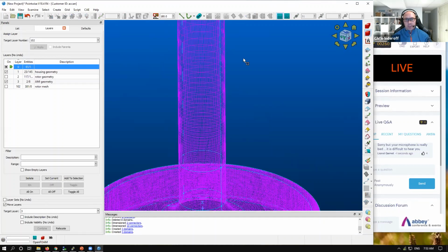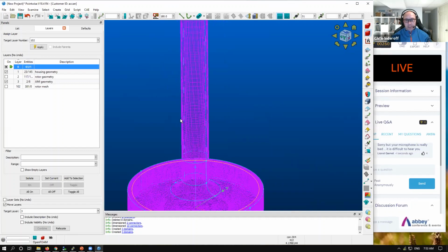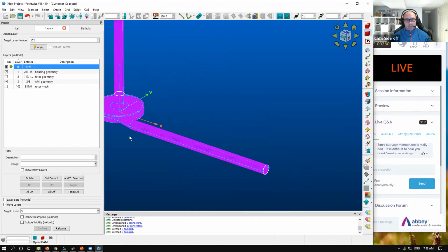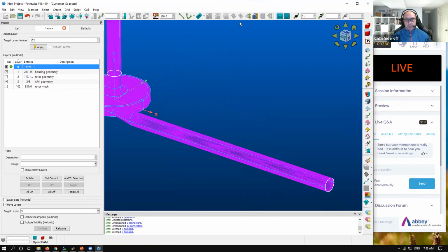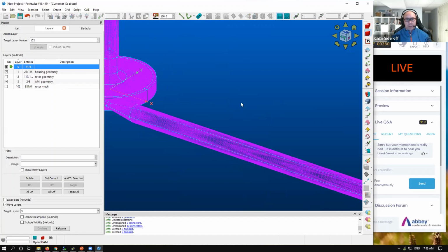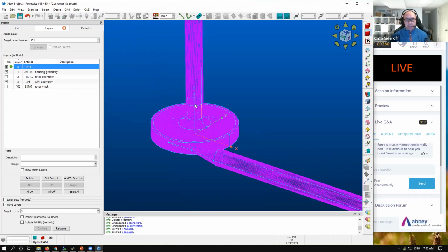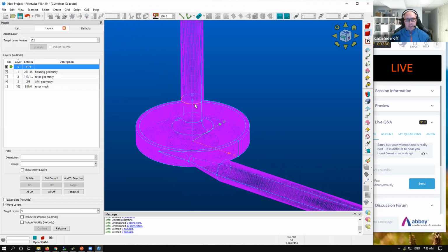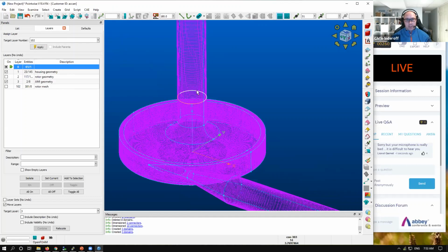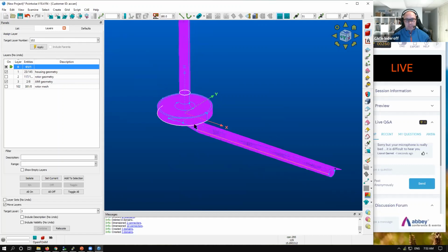The other thing I need to do is cap off these ends with a structured domain. Actually, I can't do that yet. The reason is that to make a structured domain, I need to have 4 edges, and right now at the circular regions I only have 2 edges, so I need to split these connectors into 2 pieces.